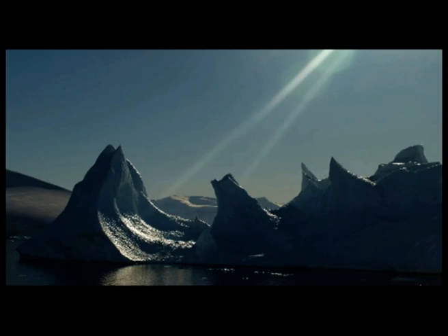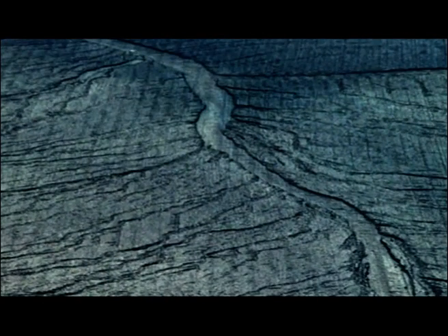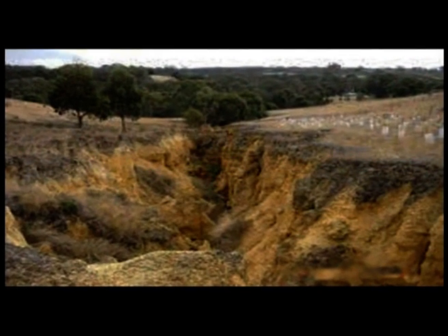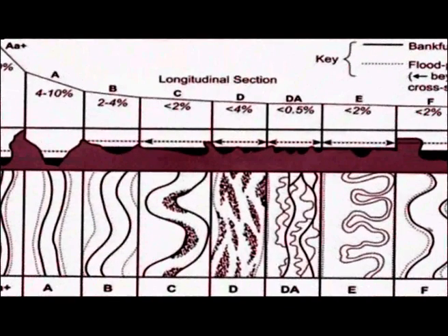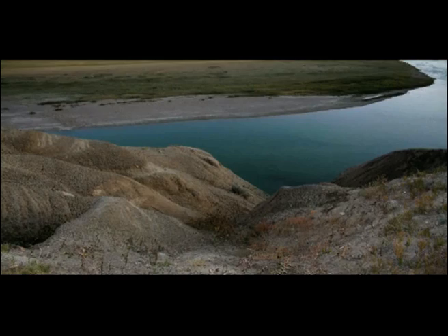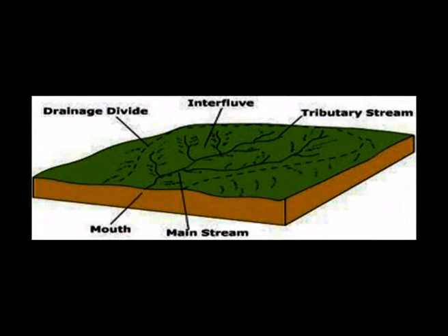Rills are shallow channels eroded by threads of turbulent flow. They are developed in the sheet flow. During rainstorms, rills erode headward on the steepest local gradient at a faster rate. On open slopes, they tend to form parallel to one another and also form dendritic patterns of drainages. Rills are ephemeral features. They may be destroyed and recreated during major storms. The rills terminate at the base of slopes and thus they are not part of the regional drainage systems.